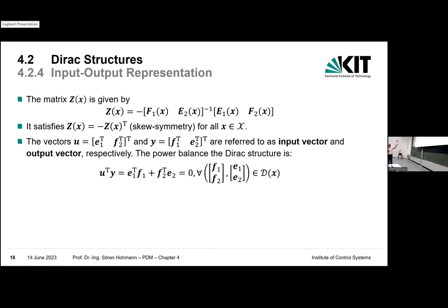Then this might not be true, but for the direct structure itself, it's power preserving. And in the explicit form, where z times u gives y, u times y is power preserving also. This is a fundamental fact. So this is something new which you might not know from your daily experience of input-output relations of the multivariable control things you learned in the lecture of Mr. Kluge. If you take any input and output variable, multiply them, you will not find this nice relation here.